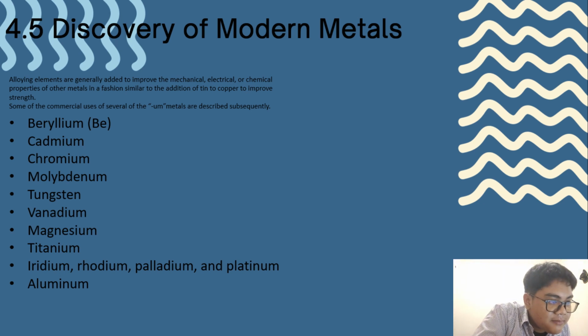This difference in melting temperature complicates combining the two metals into an alloy. Because of this high melting point, molybdenum, along with tungsten and rhenium, is called a refractory metal. The term refractory generally applies to a wide range of ceramic materials and other high melting point compounds.